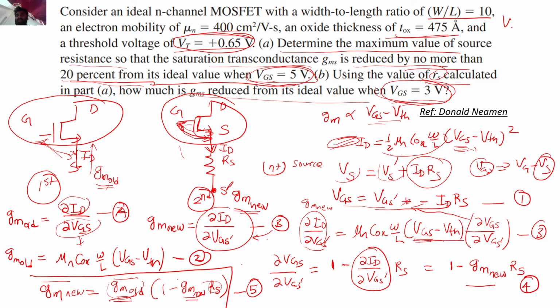So your VSB is 0 in this question. So whenever they have not mentioned anything about the body effect, right, you can always ignore it.